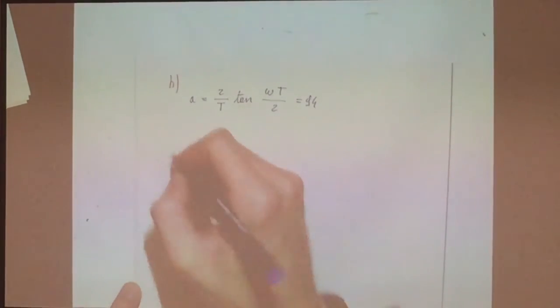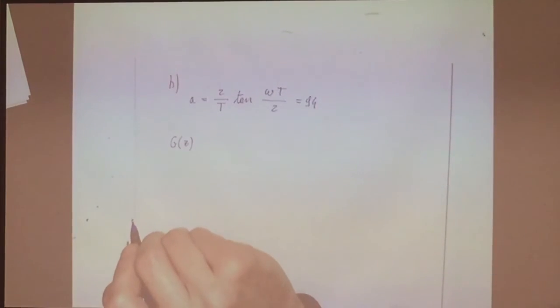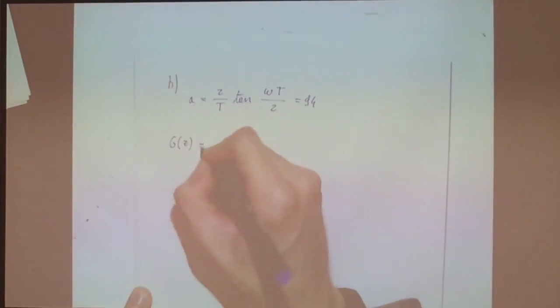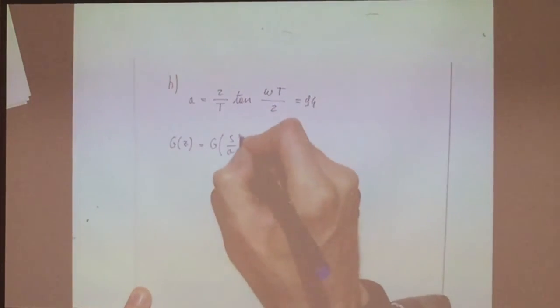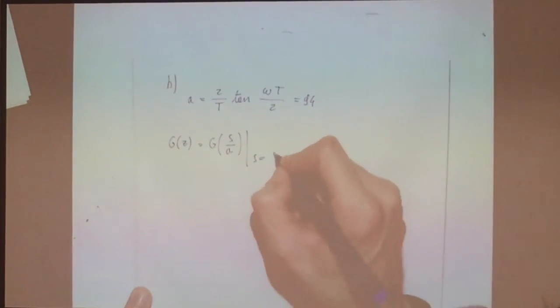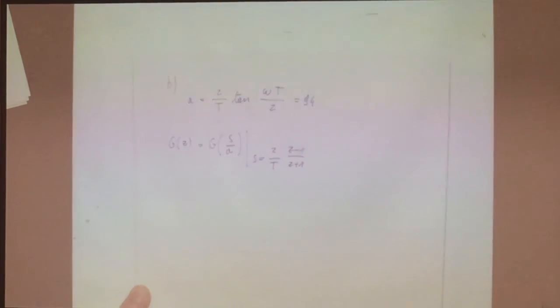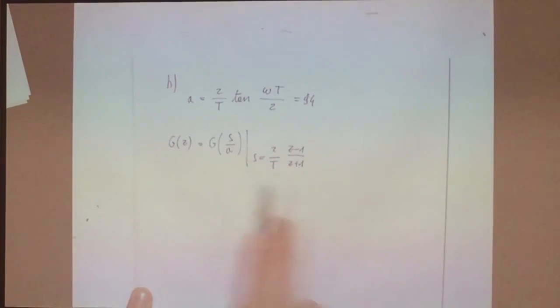And then at that point, we say that the discrete filter with the pre-warping is equal to the filter in s over A applying the Tustin rule. So applying s equal to 2 over T, z minus 1 over z plus 1. This is the pre-warped transfer function. So we apply the Tustin rule to the pre-warped transfer function rather than to the original transfer function.